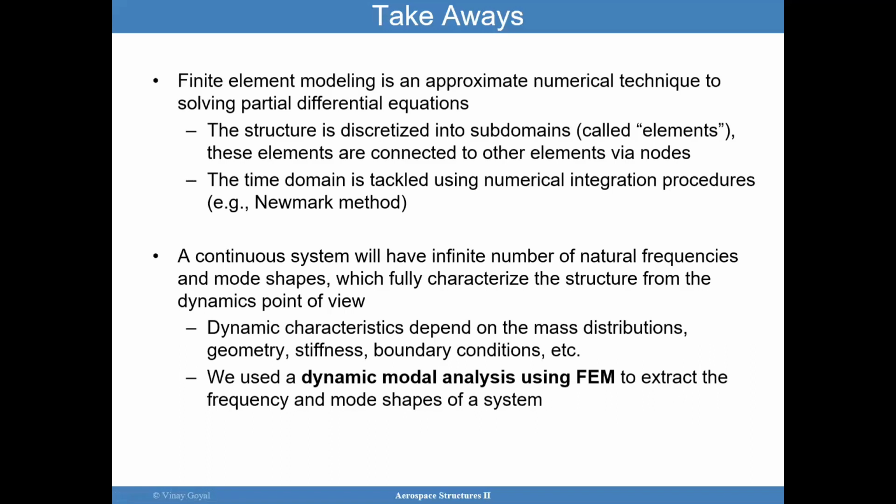A continuous system, recall from the beam example, can have an infinite number of natural frequencies and mode shapes. But when we discretize the domain, we end up with a finite number of natural frequencies and mode shapes. To fully characterize the structure from the dynamics point of view, the dynamic characteristics depend on the mass distribution, the geometry, the stiffness, and the boundary conditions. Therefore, every system has a unique behavior dynamically, and that behavior is fully characterized by the natural frequencies and mode shapes.